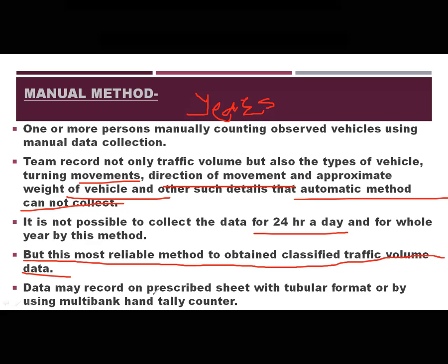Data may be recorded on a prescribed sheet. Here are the sheets, I will show you that. In that sheet, the counter or the volunteer who is standing for counting the vehicles marks the numbers in a tabular format. A multi-bank hand tally counter is also used.